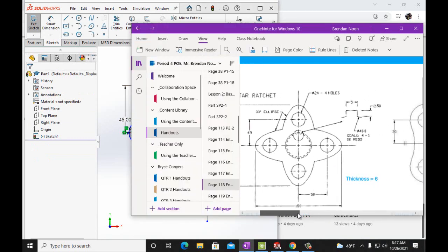Let's move this over here. So we have 5 millimeter right across here. We have a 5 millimeter, I don't know what you want to call it, a slot, I guess. A 5 millimeter slot. And we have a circle with a radius of 40. So a circle with a radius of 40, then a 5 millimeter slot right on top, and then all the way around it, a height of 2.5, and there's 18 of them.